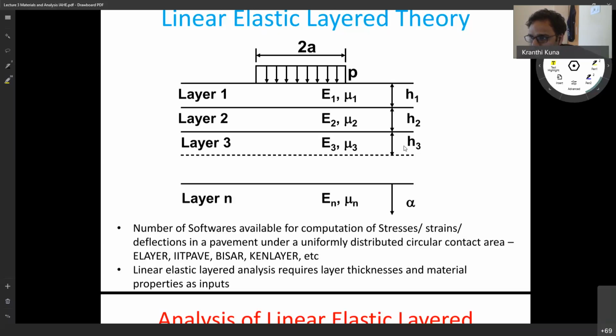I'm talking about the materials taken directly from the quarries, using GSB and WMM. With those as well, it's the same, isn't it? You carry out the CBR test, and you will not take the maximum CBR you are getting. So explicitly we are not introducing any factor of safety, but within the design process there are many ways in which we are being conservative, for example, material models.